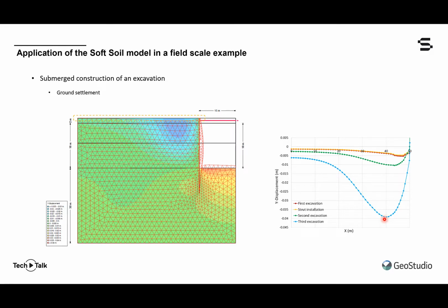The overall displacement pattern is downward towards the excavation, causing the ground surface then, you can see that it heaves. There's a little bit of heave. This is the suspicious part near the portion of ground right up close to the wall. And that is primarily because the top of the wall rotates counterclockwise back into the soil profile, causing a little bit of heave. So that aside, you can see here that the maximum amount of settlement is around 4 centimeters at about, right in the middle of this contour.